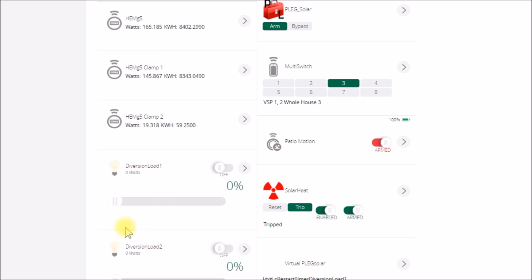So just like the sharing mode, I also added this assist mode, which is basically the same logic as the sharing mode, but the idea is if this light dimmer got up to 100% and I couldn't use up all the excess power and I had 200 watts of excess power, I have this assist mode that the dimmer on line 1 could jump in and go up to 200 watts and use up the excess power that's down here.